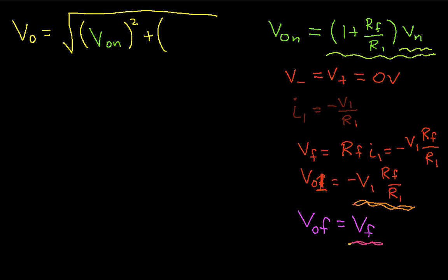Again, the reason for this is that when you're dealing with noise, powers add, and you need to take that into account when you look at total noise voltages. So it's not noise voltages that add, it's noise powers. Okay, so basically what we have here then is the 3 noise terms. And we've squared each of those, and then we'll take a square root.